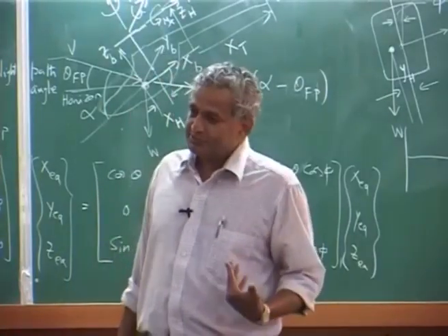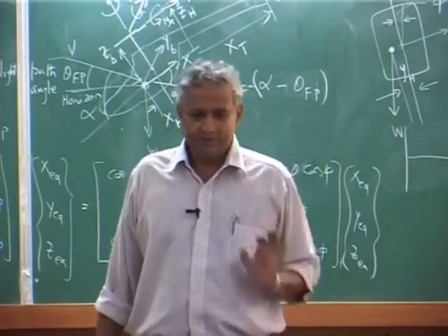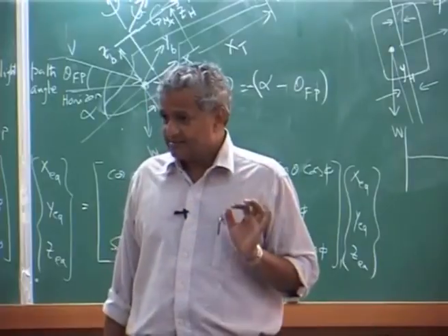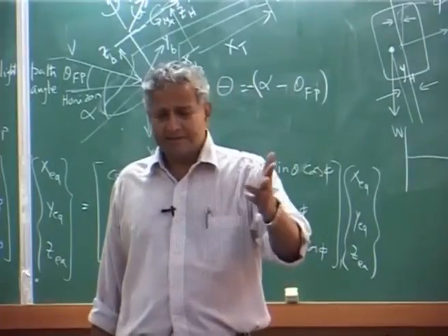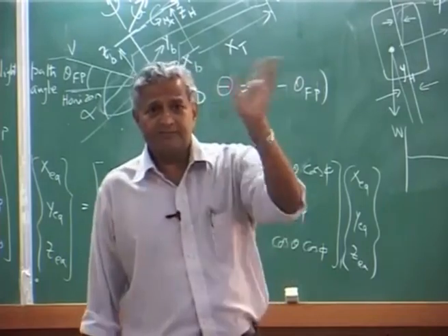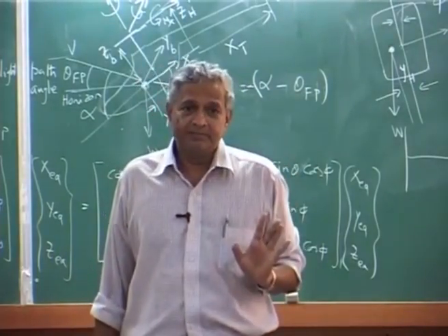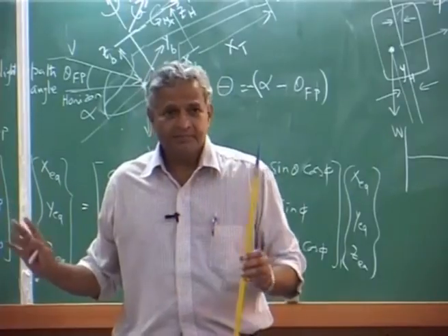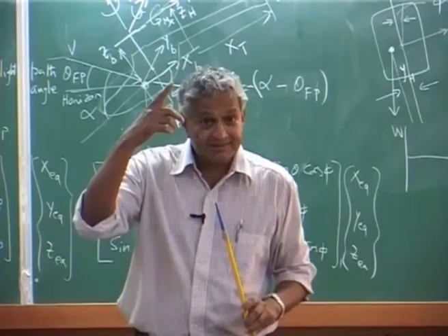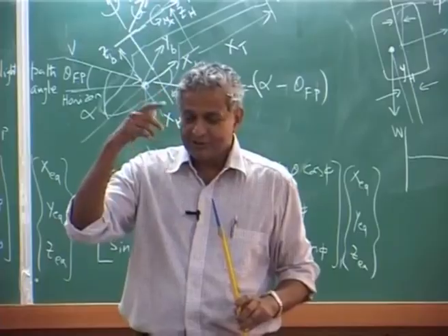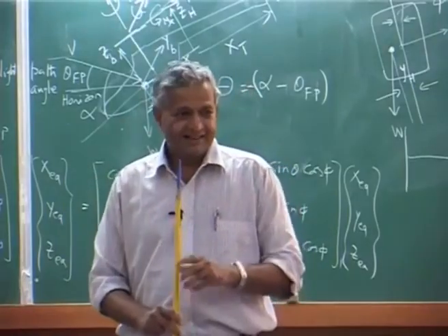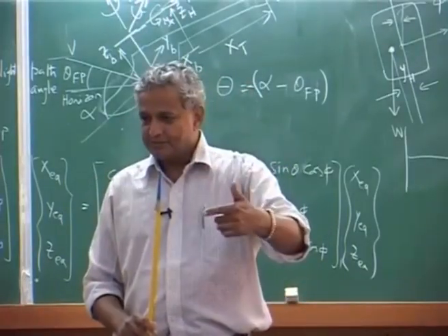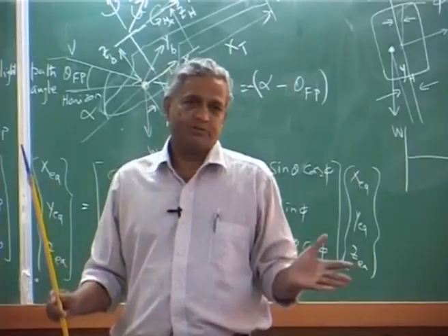In the wind tunnel, what people do is they give prescribed collective, prescribed cyclic, prescribed theta naught, 1c, 1s. Now, find the response of the blade. But for that you need to know the inflow, so they will give the shaft angle, that is all. But you do not know the thrust, you follow. So, you have to get the thrust and then get the inflow and then get all the response quantities.